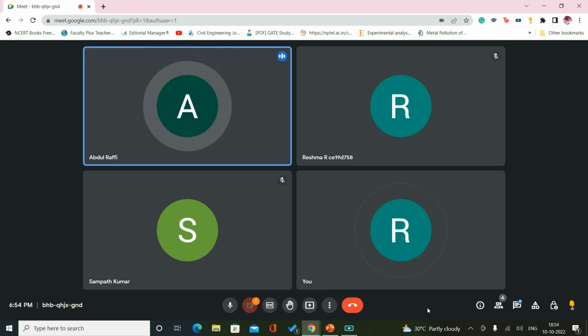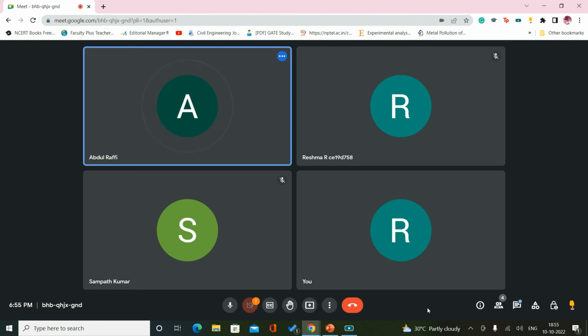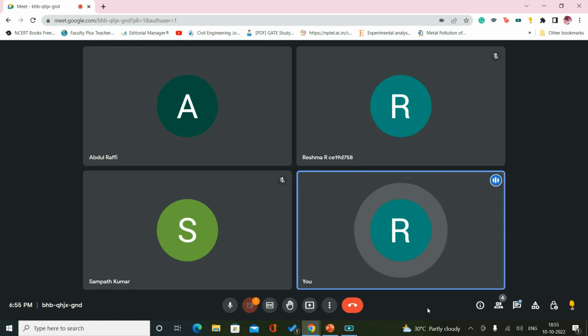Yes, that is correct, madam. Non-yielding wall. Tension will happen only if one force is pulling something out, right? Yes, madam. Since that is not happening here, we can't say whether the soil is in tension or compression. There is no such thing as the soil being in tension or compression when the retaining wall is at rest.